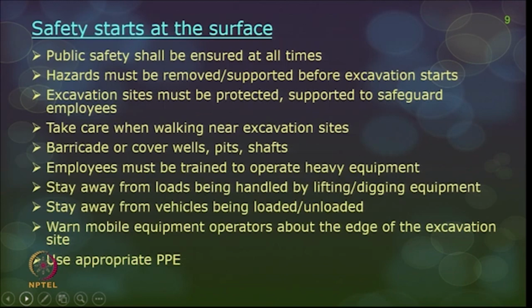When mobile equipment is operated close to the edge of the excavation site, you should stop those processes, because the vibration of that equipment can disturb the soil which you have cut, and use appropriate PPE. So, these are generic steps which you should keep in mind before you start with your excavation. Now, let us talk about the actual excavation and where cave-ins are more.